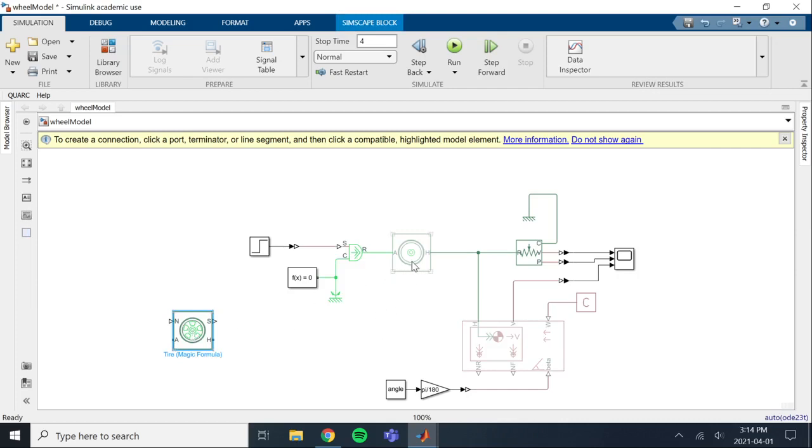So this tire does not take into effect any sort of rotational resistance or effects of normal force on the wheel, any deformation based on the mass itself. And it also doesn't take into effect traction either. It does this solely based on torque and what it's pushing. This magic formula tire, we can actually specify how our tire interacts with the ground using different parameter values.